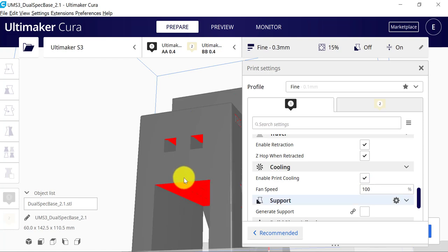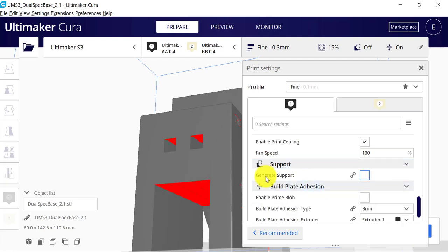You want to be a little bit careful because with certain materials, PLA is pretty good like this, but with certain materials, if you cool it too much, then it's going to start to stick to the print head and it won't actually make it to your model, and you'll just get a bunch of gunk or buildup on the tip of the print core. And so for other materials like ABS, these things will change. PLA is pretty forgiving.